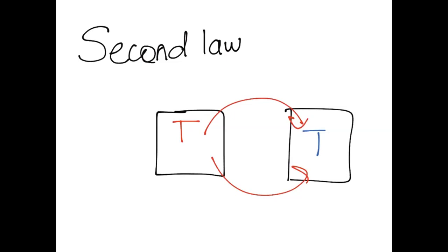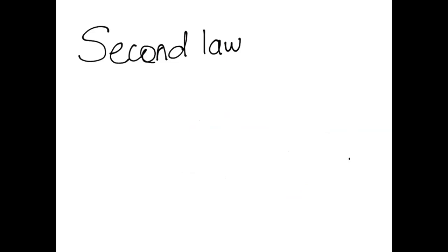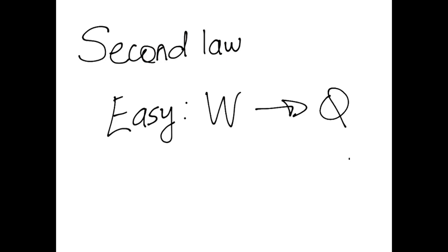You might actually understand now that the heat is going to be transferred from the high temperature source to the lower temperature reservoir, let's say. And this is very natural. What fixes this direction is the second law. The second law limits the performance of any system. It is very easy to turn work into heat, but to turn heat into work is not that easy.